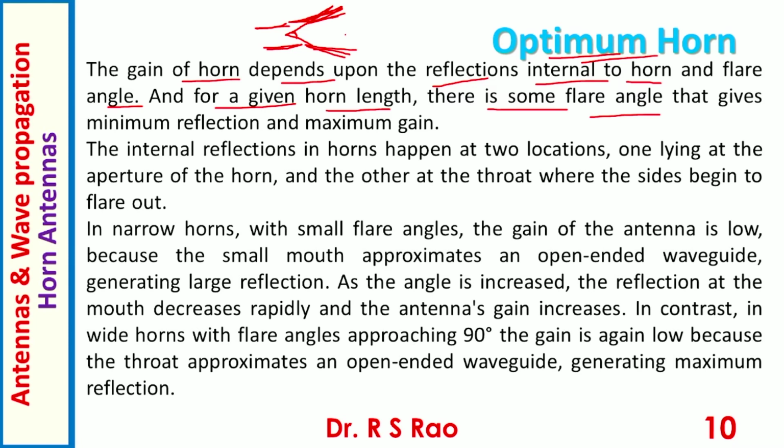When the opening is more and more, the flare angle also becomes more and more, and gain also increases, becomes larger and larger. But this state of affairs continues up to a certain point. If the flare is further increased from this point, then gain starts falling down due to beam splitting.